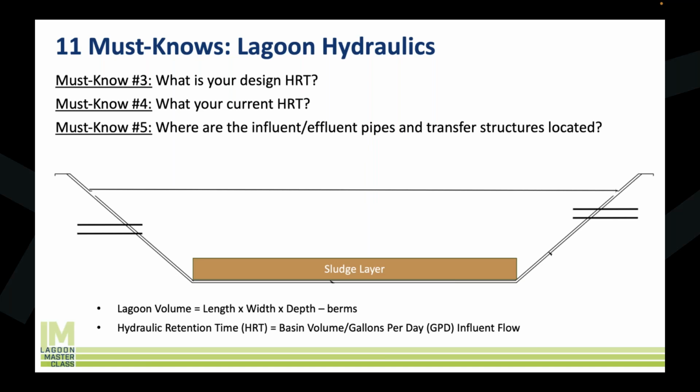So again, I've been to hundreds of lagoon sites. Lagoon sludge, it's right up there, man. It's probably one of the top issues, probably one of the leading causes of lagoon problems, that the lagoon was built 30 years ago. It has sludge buildup on the bottom, which is the design of the lagoon, is to store biosolids at the bottom, by the way, and it's never been removed. So in some cases, I've seen lagoons that are 50% full of sludge. So think about that. You had 60 days of retention on day one, and now you have 30.